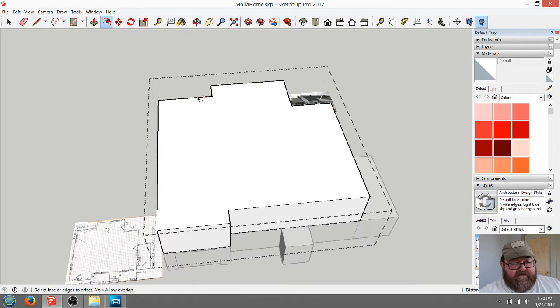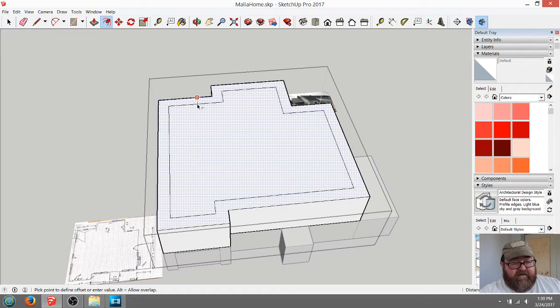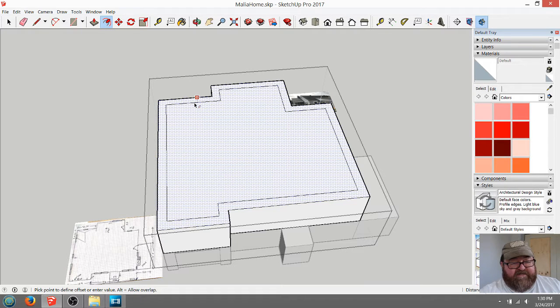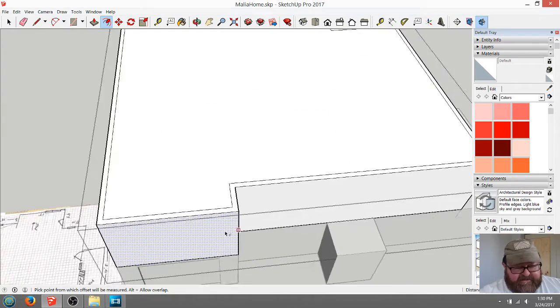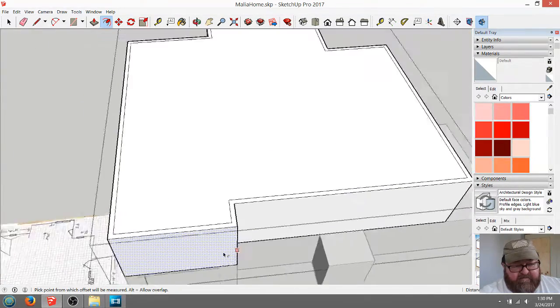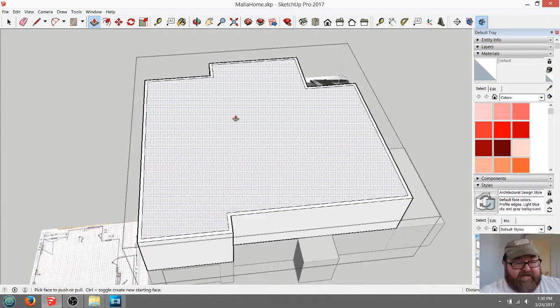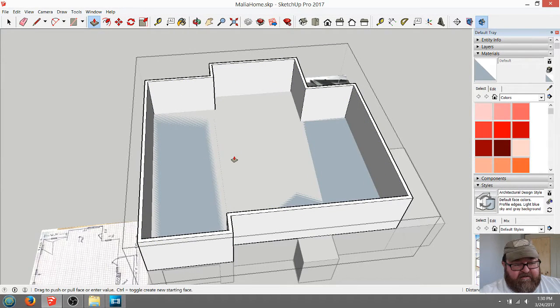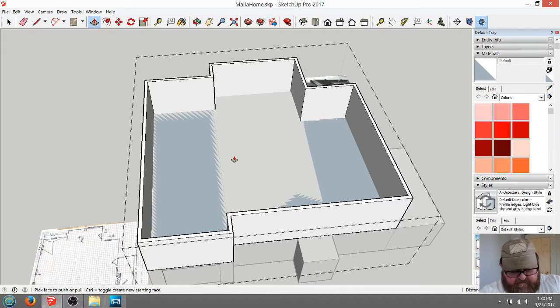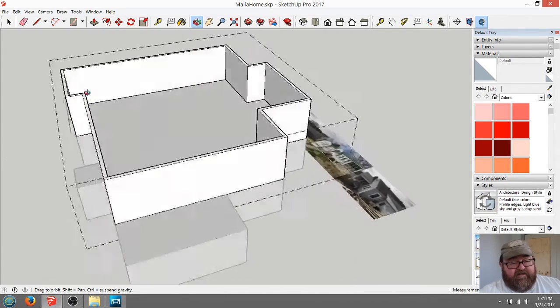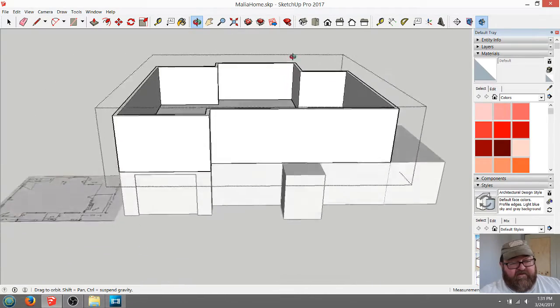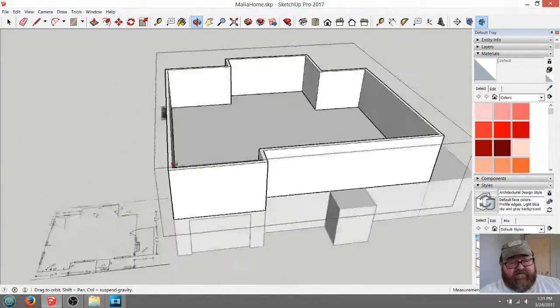You can go in here and select that outer band. If you think your walls are like 5.5, 6 inches, for now I'm going to say they're about 6 because I know there's plaster on the inside. So you can offset that 6 inches, and you see I just created basically walls all the way around. And if I take this back down to 8 feet 1, it'll basically disappear. And you see I just that quickly created my exterior walls for the main level.